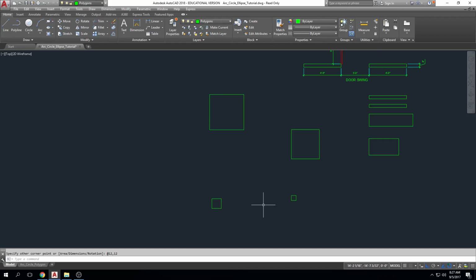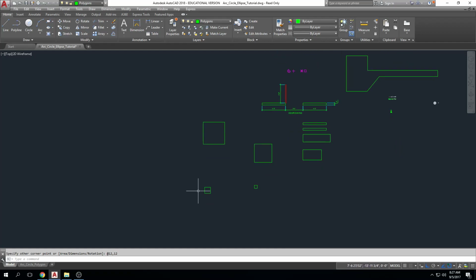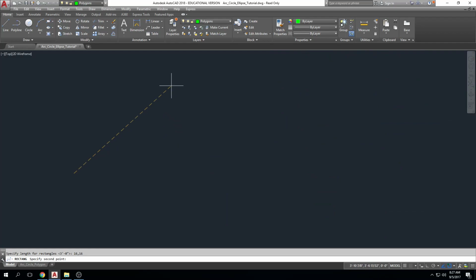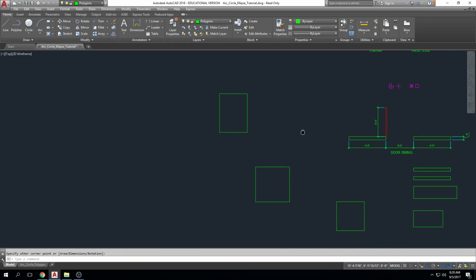Okay, so freeform input, we've got the @12,12, and then the final input to create a rectangle. I'm going to click my first point, and click on dimension, and we could type 16, comma 16, enter. Oh, no, sorry. I got confused in my inputs there. Let me start that over. Rectangle, click, dimension. I'm going to type my first dimension, something like 36, enter. The next dimension, 48, enter, and there's my 36 by 48 rectangle. And of course, I just have to input where I want it to rest in the quadrant. So click, and there's my rectangle.